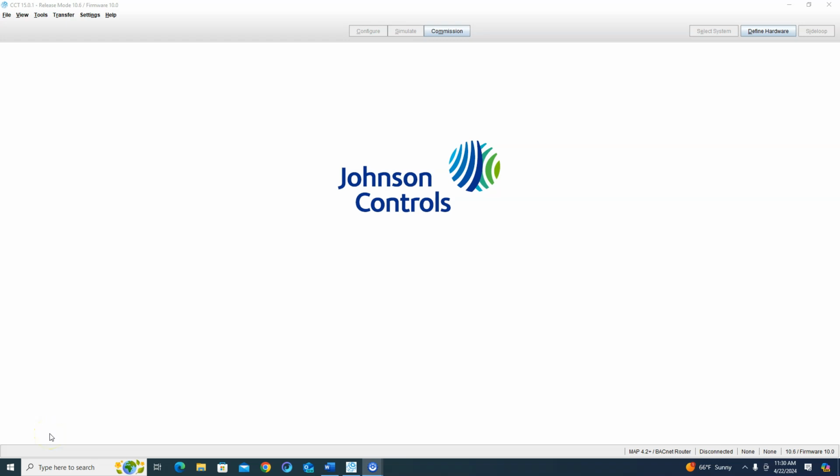Hey everybody, today we're going to talk about how to do an air pressure reset in CCT. Now normally this is done at a supervisory level, like in LCT if it's in an NAE, or if it's in a JACE, it's done in Niagara programming, but it can be done in CCT, especially with peer-to-peer. You can peer-to-peer your VAV boxes back to the air handler controller and do it based off a damper.